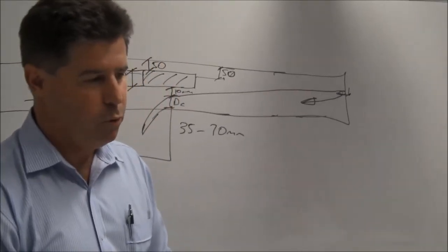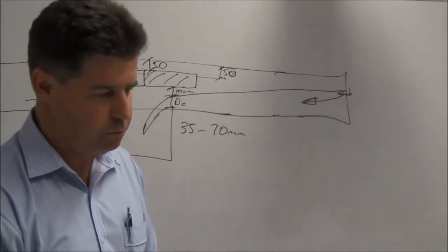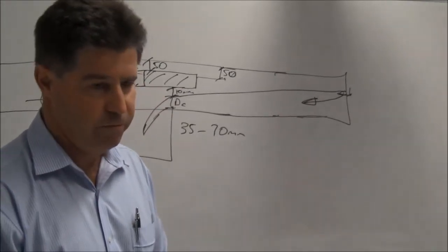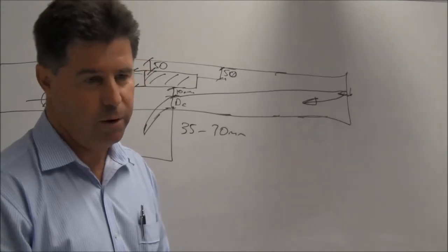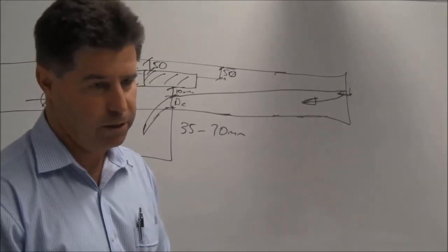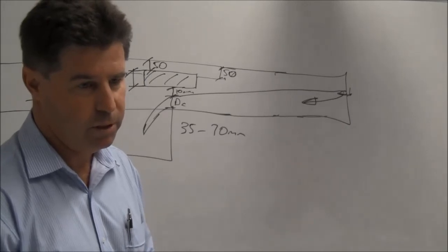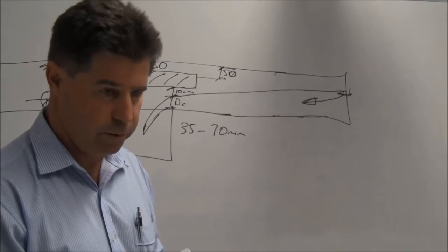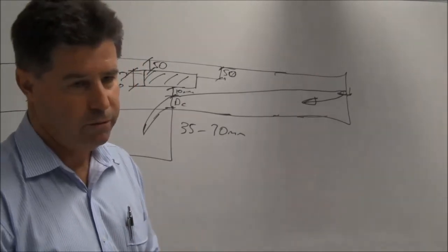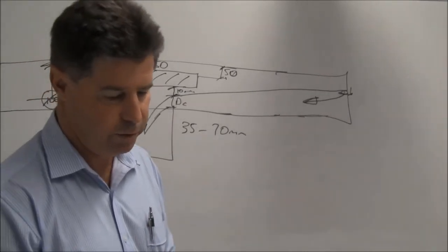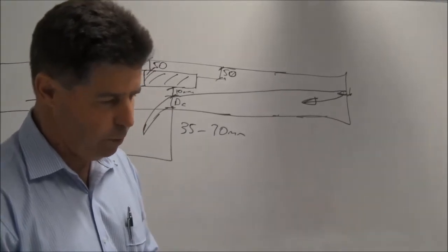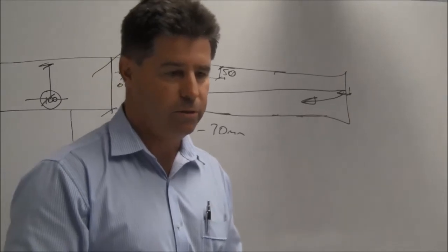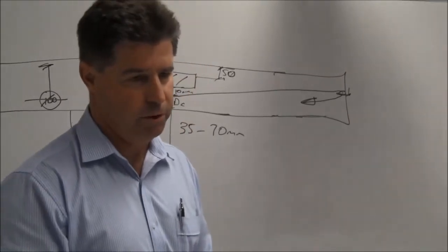It's for wind action. If you imagine the water in the box gutter is completely full, and it's a very windy day, we don't want that water to overflow out of the gutter either. So we have a 50 mil freeboard at all times. Some people use more. The freeboard makes sure the wind effect doesn't push water over the top of the gutter. We want the overflow to work so it discharges safely, but we still don't want the water to overflow into the building at all.